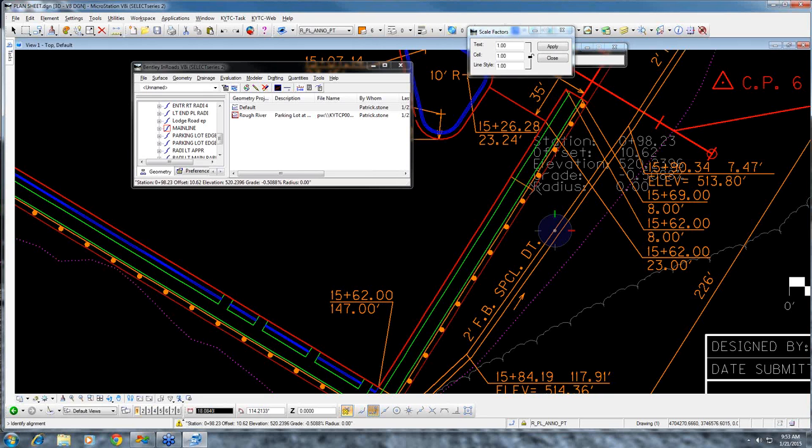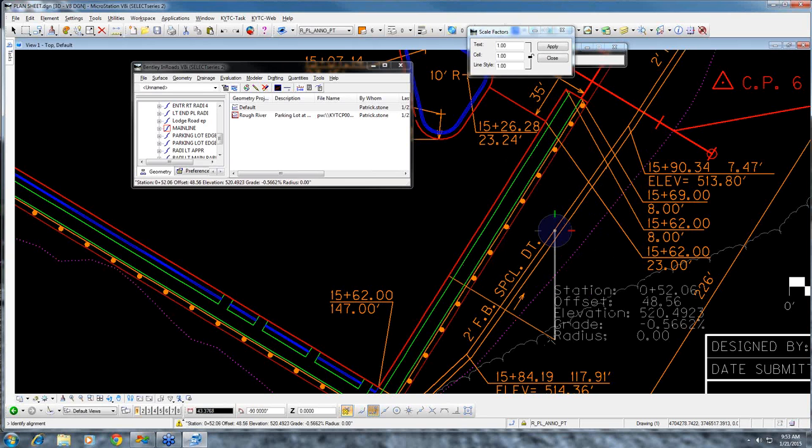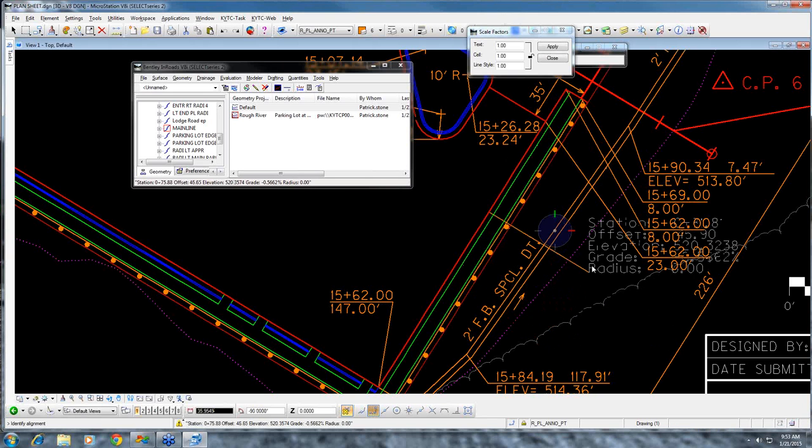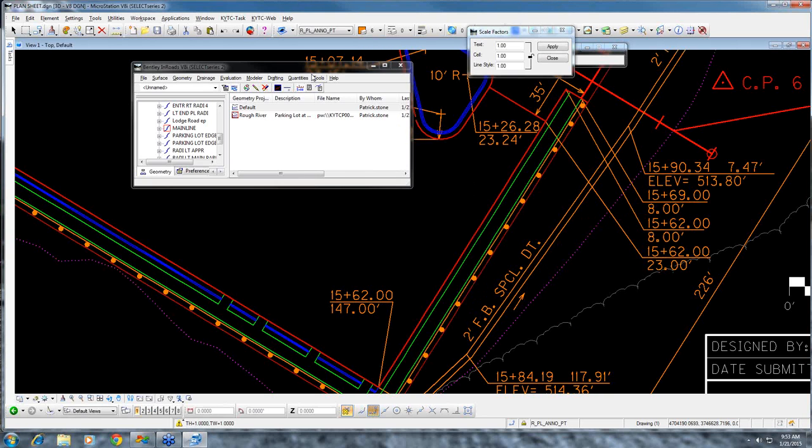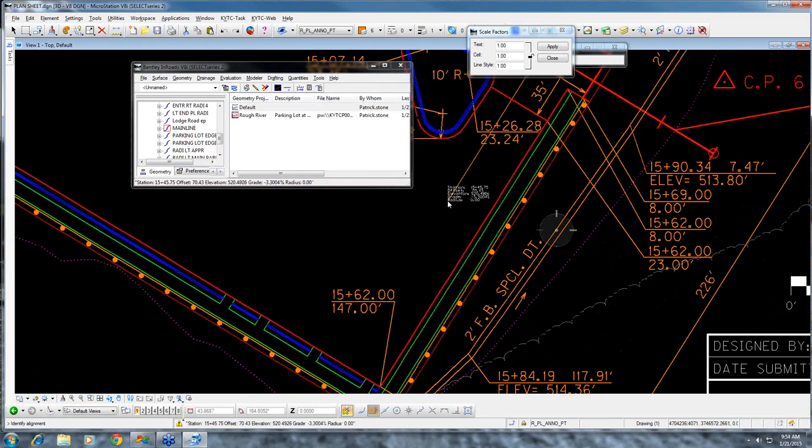All right, thanks, Patrick. One thing I've gotten a question on before is the text displaying there. Sometimes the text is just enormous and in the way, and what that text is pulling from is the text height in MicroStation when you're using the horizontal vertical alignment tracking as opposed to the generic tracking. So if you don't want to see it, just make that text height really small and it'll go away. Yeah, I just change the text height and make it smaller, or you could make it a fraction, just like Jason says, microscopic, if it's annoying you.